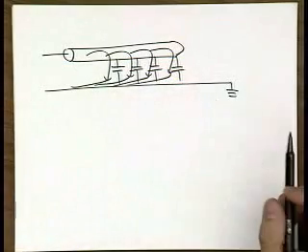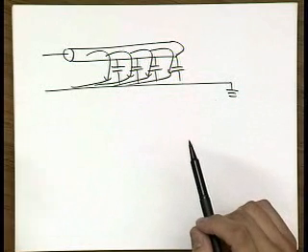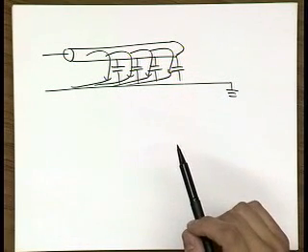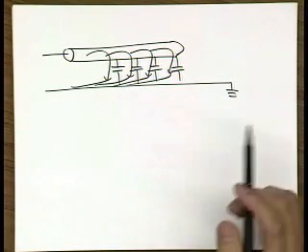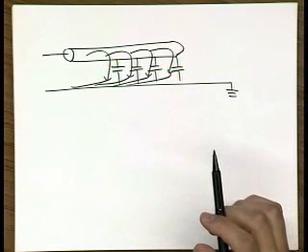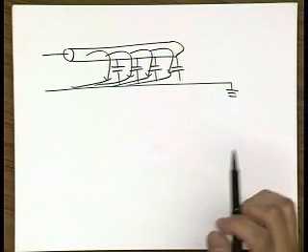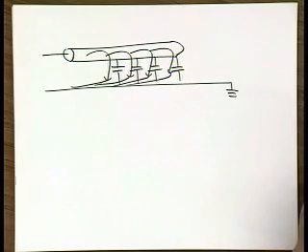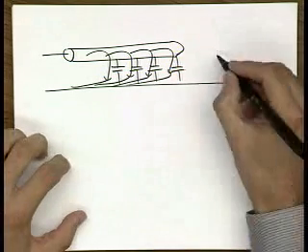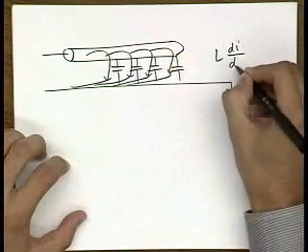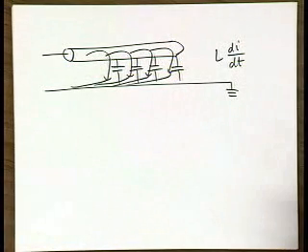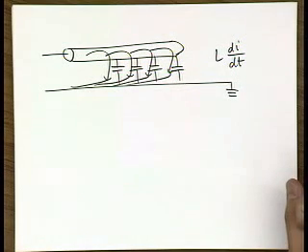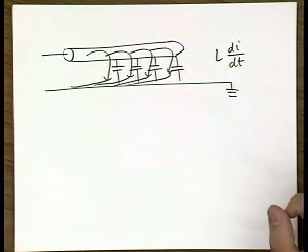So now what these inductances will cause you is ringing and overshoot, reflections due to impedance mismatches, inductive coupling, and also switching noise due to this L di over dt. So now the question is, how do we really analyze and extract equivalent inductance?